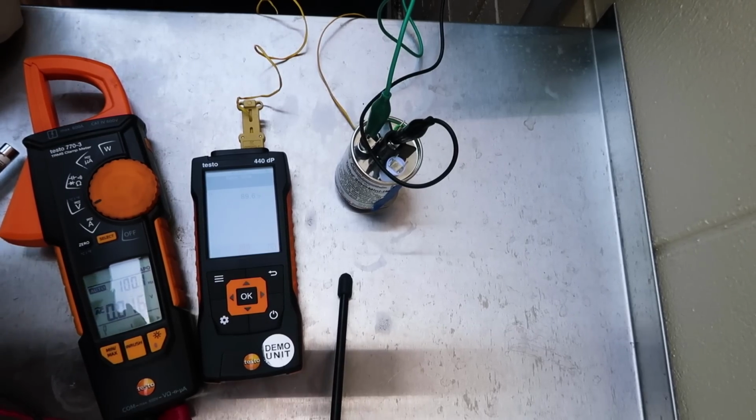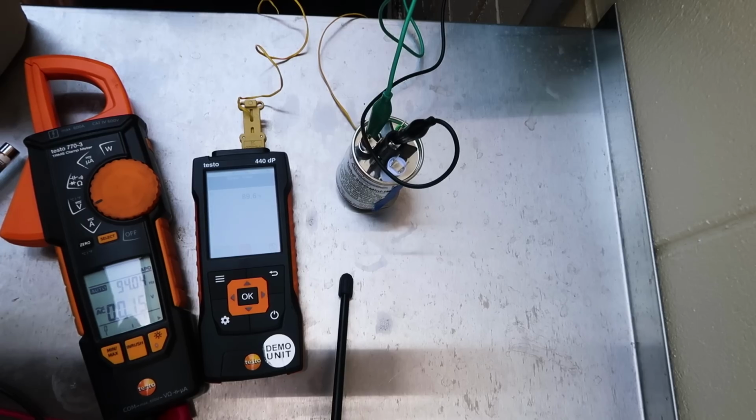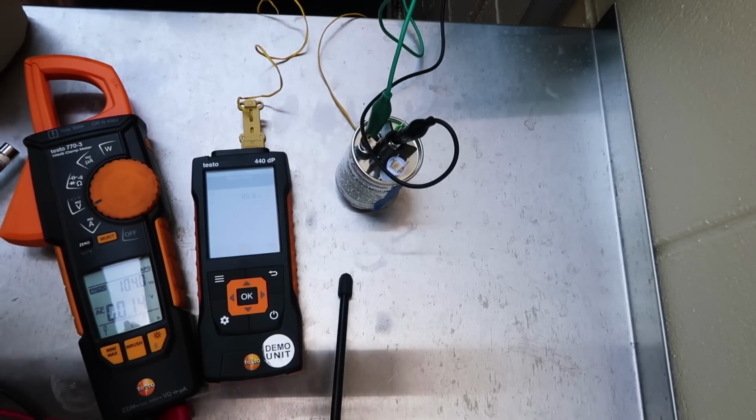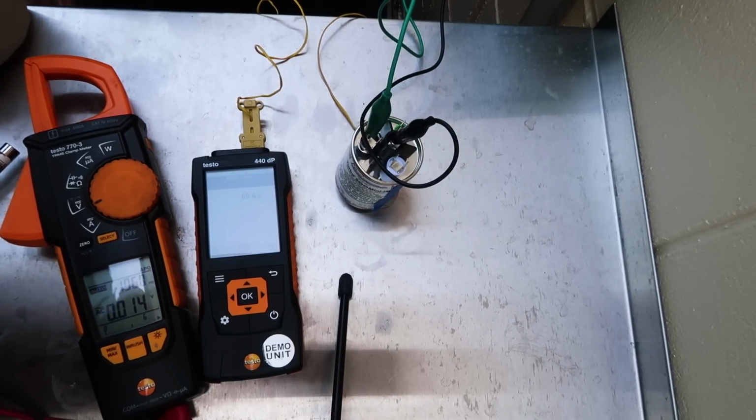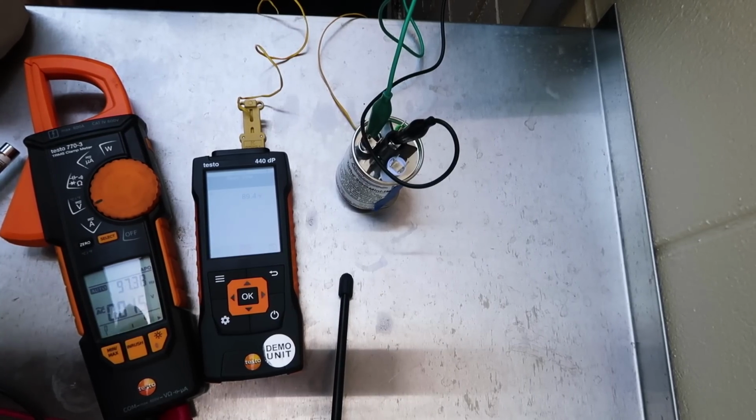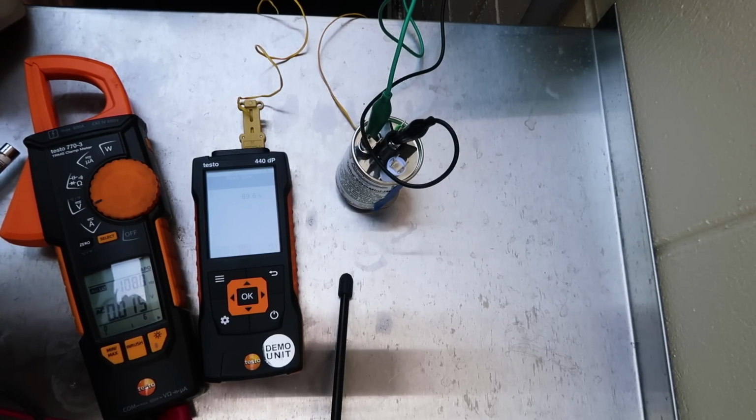For example, if you have a condenser fan motor that's failing, and because of that your entire condenser is running hot, well then your capacitor is going to run hot too, because of the increased ambient temperature around the capacitor. So what we know is increases in voltage cause capacitors to fail prematurely, and increases in ambient temperature cause capacitors to fail prematurely.